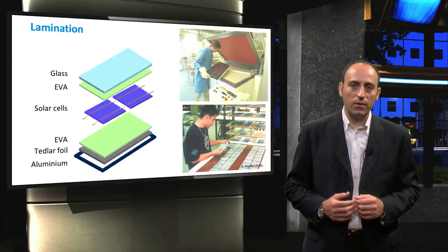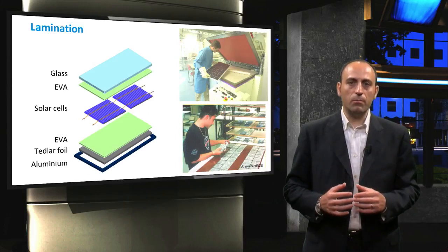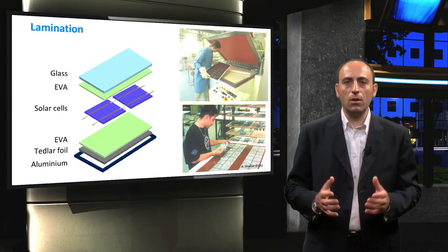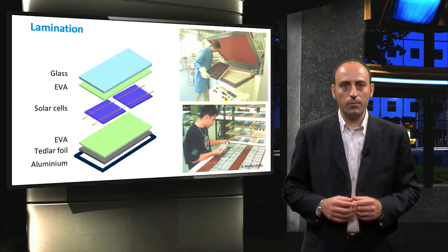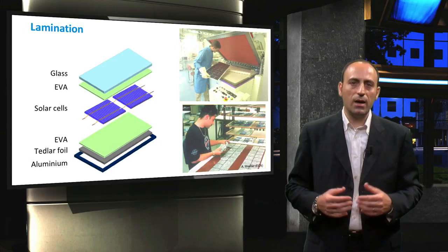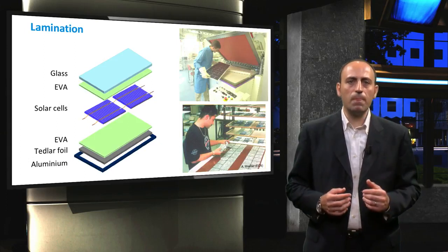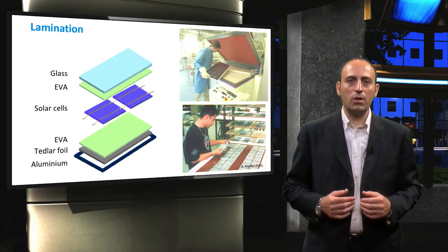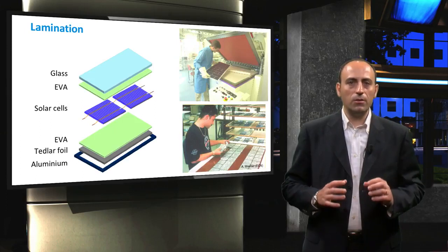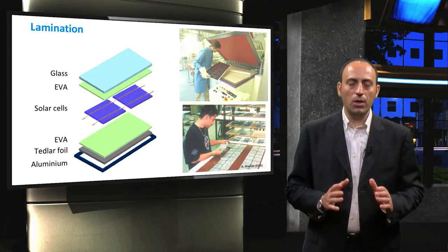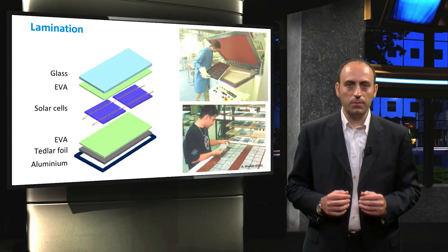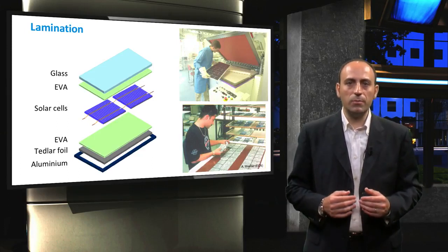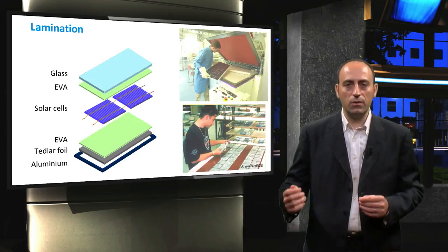As solar cells are interconnected, the following step in module production is the lamination, which we will briefly explain using EVA as an example. These are pictures taken in an R&D lab a number of years ago. Nowadays, of course, the production lines are fully automated, but the principle remains the same. In general, there is a backplate where all the cells are mechanically placed. Then the interconnection strips are soldered from one cell to the next.